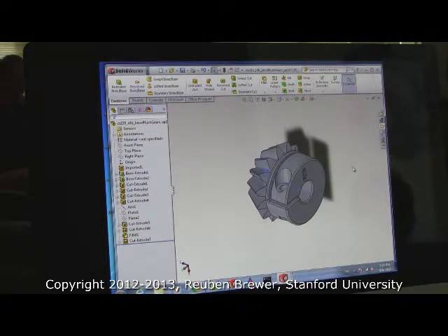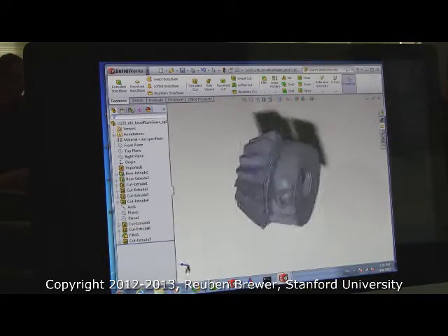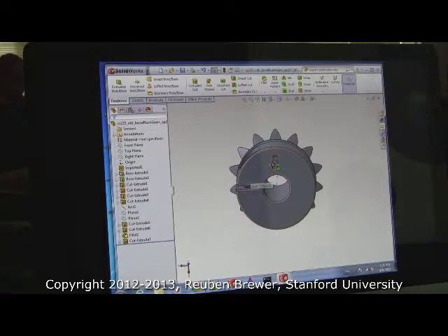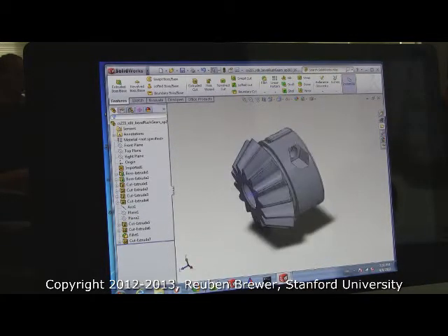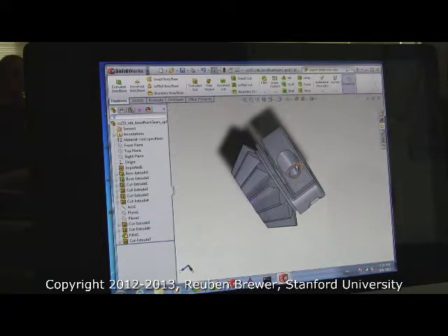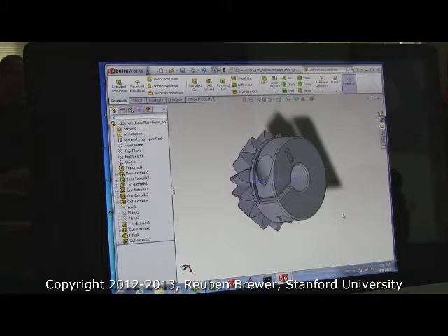Okay, so let me just explain what this does real quick. So this axis is the direction we're going to stuff a shaft through. The reason you see this little thingy here, see how it kind of sweeps over? That's a clamp. So we're going to put a nut here, and we're going to put a screw here, and then when we tighten it on the shaft, the gear won't move with respect to the shaft. We could do a set screw instead. Anybody know what a set screw is? Or you just screw it in so it's actually touching the shaft. Yeah, if we had the screw touch the shaft, it would mar the shaft. So then we'd have to put it flat, and that's a pain.